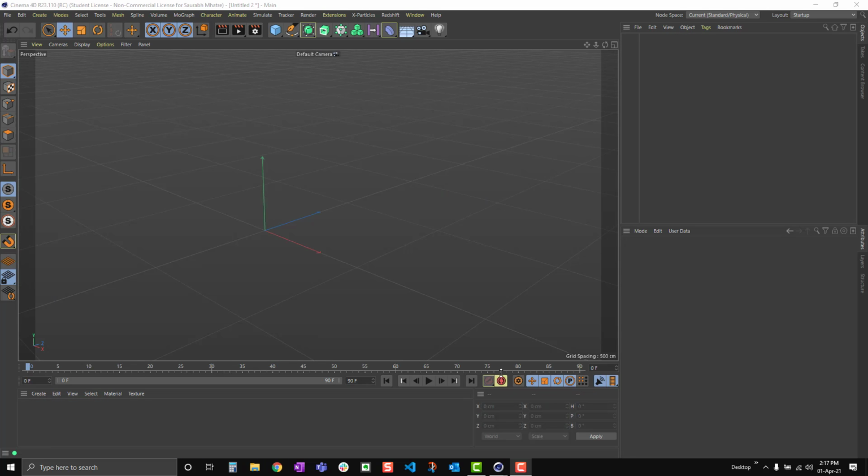This area of the interface is called the animation palette. This is the area where you would control, edit, and play your animations. Right now you can see this area which shows 90 frames. It determines what is the last frame of your animation. So your animation timeline right now is 90 frames. You can easily edit it by just typing in it. For example, if I say 120 frames, that's how long my animation would be.